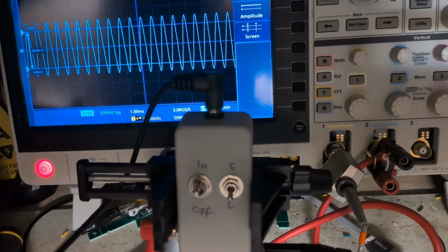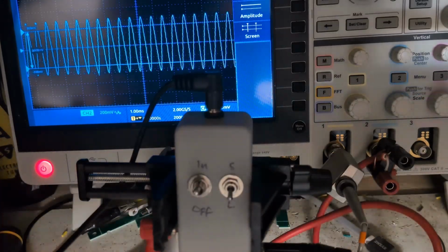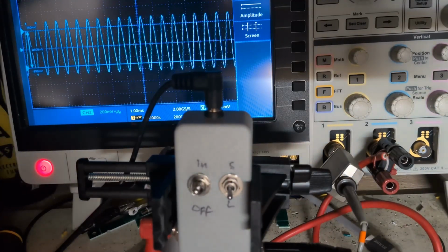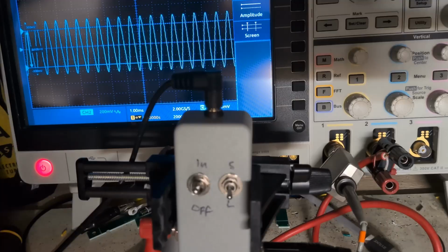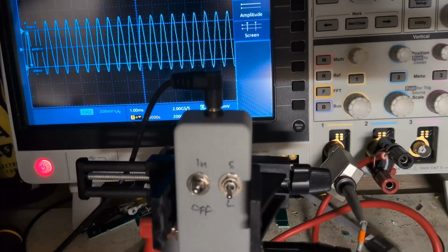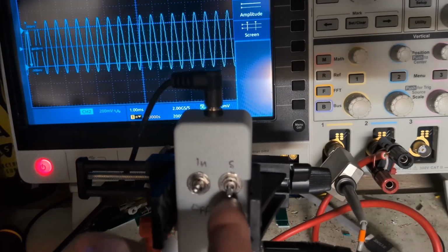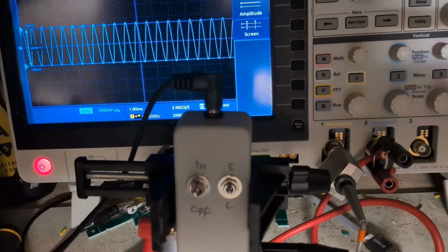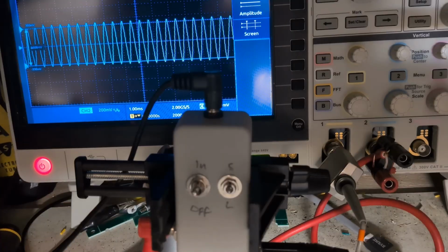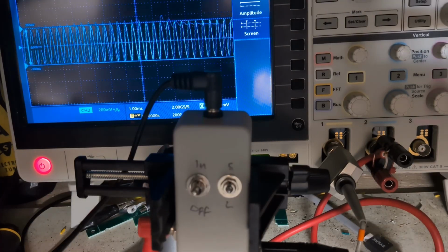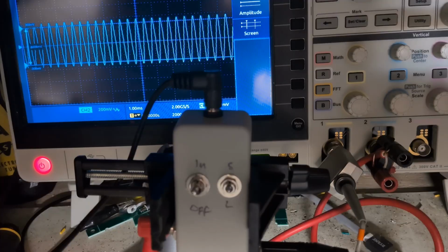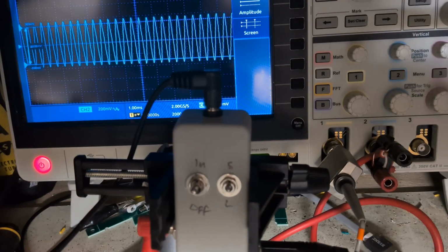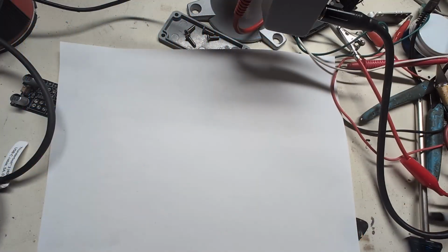And so the resonant peak there is about 1.5. So it kind of goes flat, then up, peaks at 1.5 kilohertz, and then goes down. So I'm going to draw that in a second, but let's put this switch in the up position. Increase the frequency again. And there we saw a peak at 2.1 kilohertz. So that's quite cool. Let's sketch out what we saw.